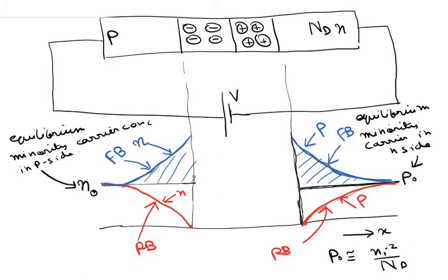And then when the diode gradually moves from zero bias condition to reverse bias condition, the total minority carrier concentration just outside the depletion region must be removed. Okay, so the minority carrier concentration during the reverse bias profile basically looks like these two graphs over here.